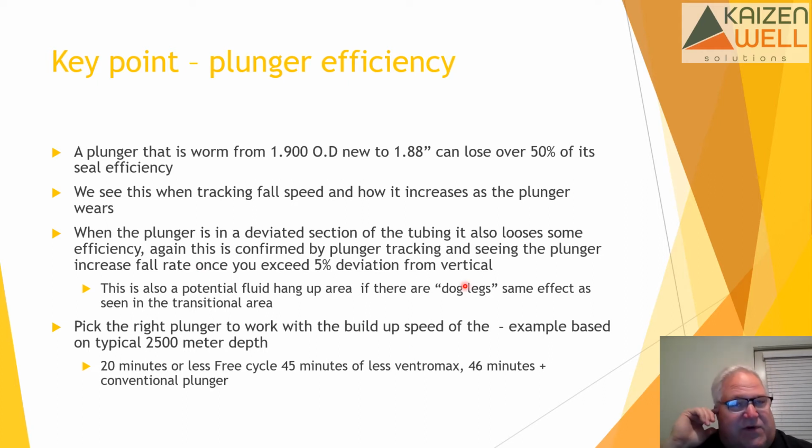It's interesting when we're following plungers that might be dropping and then they get to just a dog leg in the well and it kind of kicks over and it goes straight again. We'll actually see the plunger speed up going through that dog leg, even though you think they'd slow down because they're laying against the tubing wall. But really what's happened is they just fall against that tubing and there's so much bypass area created over the top, or there's less restriction because of the plunger when it's falling in a nice vertical, it's shaking them.